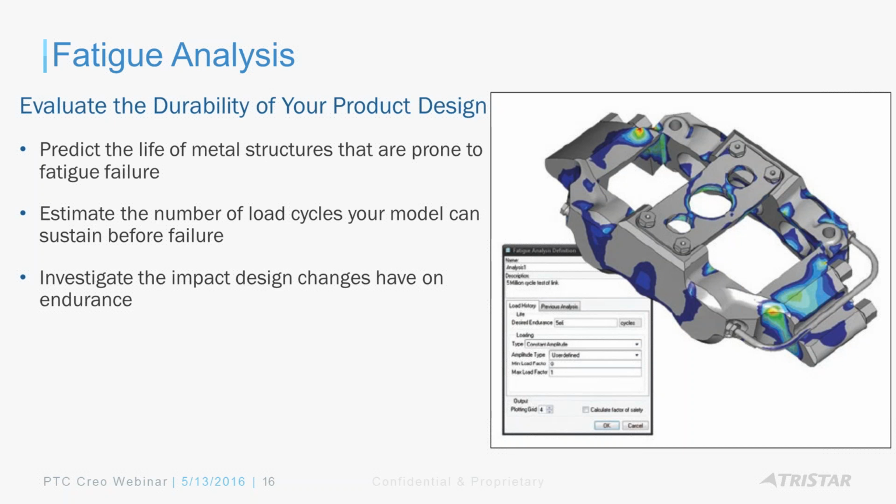And then if you're doing a durability study on your design, so I have my assembly or part where a single application of the load, obviously the stress is well below yield. However, if I apply it 1,000,000 times, in how many cycles, right, is there a chance of a crack to start, right? We're not getting into the crack mechanics or the crack growth, but all you might be interested to know is give me the confidence of life, or let me know if a crack might start within a certain number of cycles, and it's going to inform you that, right?